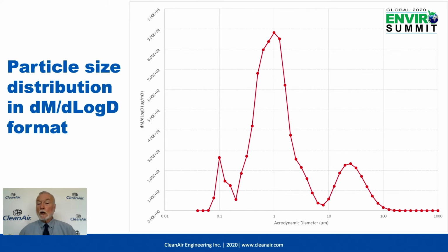As we move down, we see this large peak here, right around a micron in size. This is a process generated like combustion. These are combustion products. They could be some other chemical reaction, but they're usually significantly different than the material in the original. Then when we come down to the small peak here, you see we're down at 1/10 of a micron. This is usually vapor phase condensation, where a gas, when it reaches a certain temperature, precipitates right out of formation and forms usually submicron tiny spheroidal particles. So that's a classic trimodal distribution. By looking at this right away, you can see there's a lot of material here that's a micron in size. And if I need to lower my emissions, I need to really damp down this peak.